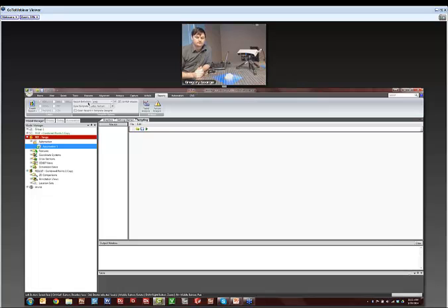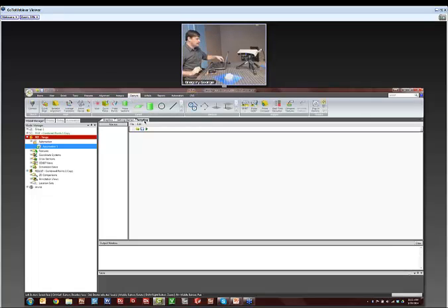Can you please explain, when you have a moment, how the scanner is connected via RJ45 network? Can you just once again walk through how that scanner connects? Yeah. So it has a Cat5. There's a custom connector here on the scanner, and inside of this cord there is the power and Ethernet. And we're running with a static IP set up right now to the Ethernet card.